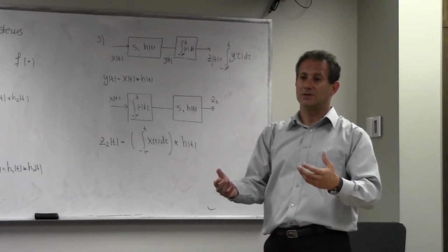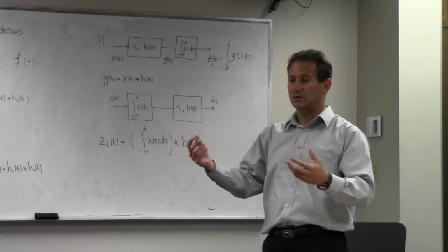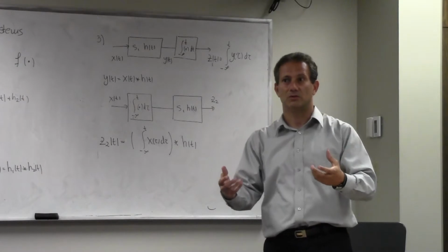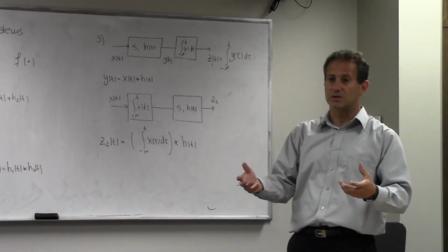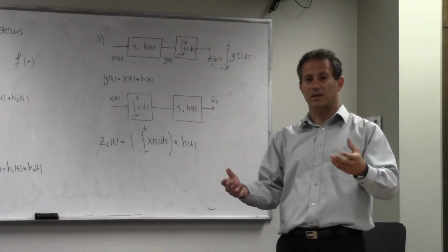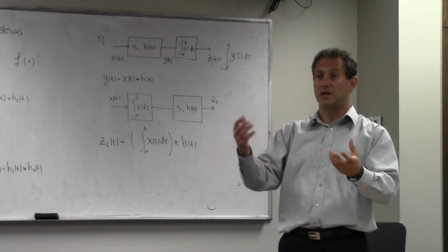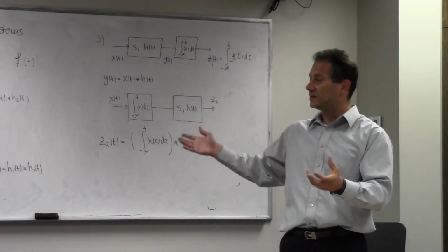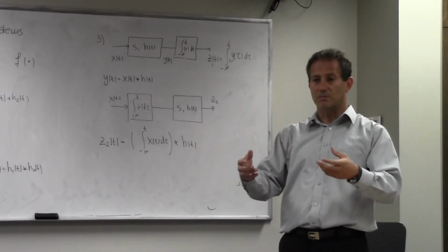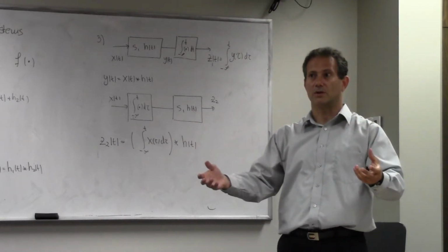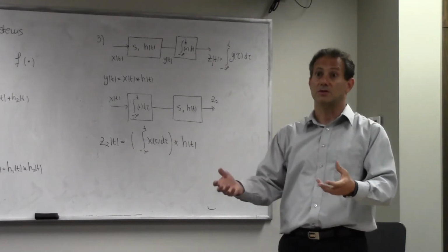But mathematically, it's much more elegant and easier, and cleaner notationally, if you say what I'm sending is a complex signal that consists of two parts, xi plus jxq. And there's some math that shows that you can model the actual response of the channel as a complex response.